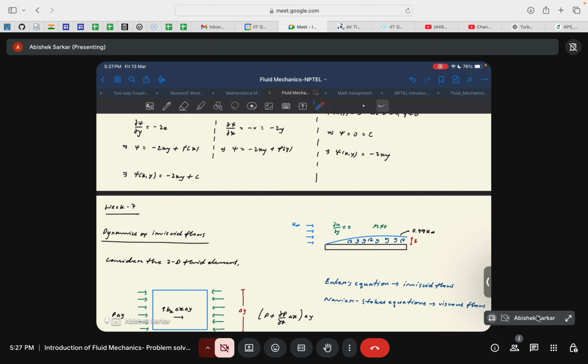Because the boundary layer or the viscous region is limited to a very thin finite region, and most of the region away from the car, just a few millimeters above it, is essentially inviscid, the analysis of these regions becomes very, very important. Finding a way to understand the flow in these regions, where the effect of viscosity is negligible, becomes very important.